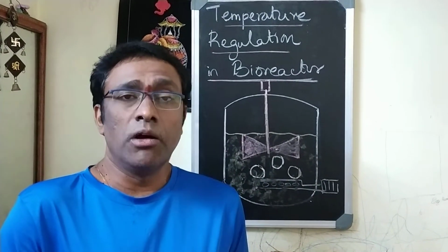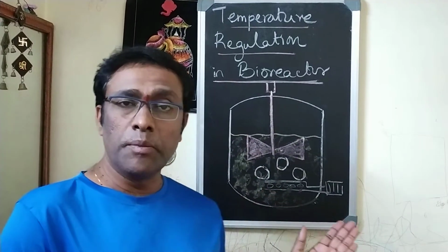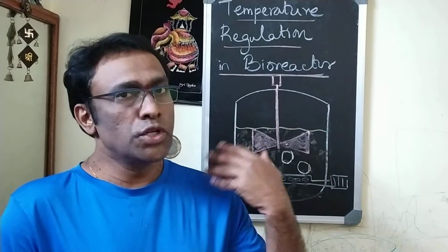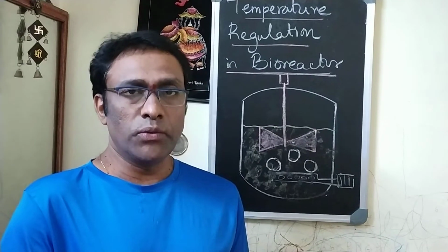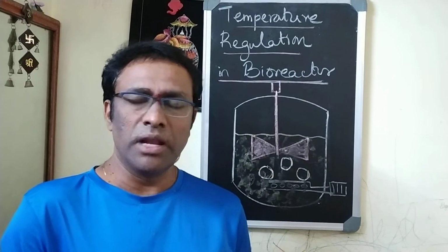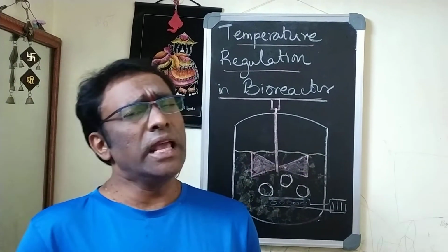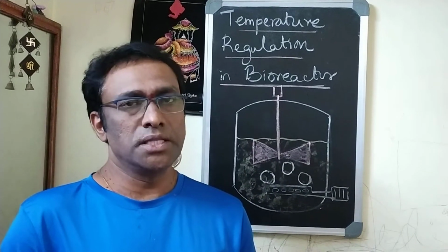Imagine alcohol production, where alcohol is the product produced by yeast in the fermenter, and we are going to recover the alcohol. We should be extremely careful about the yield. Otherwise, what will happen if temperature increases? There is going to be vaporization, and recovery will definitely be reduced. So in every fermentation process, we have to understand that temperature is important.